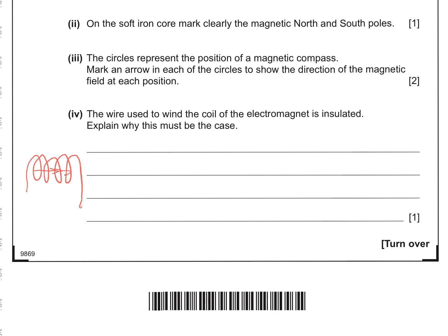Okay, so you're going to want the current to flow around the core and not have short circuits, reducing the looped current. And you certainly don't want it making contact with the iron itself and the iron starting to short circuit the coils and losing all your strength of magnetism. So the coils touching each other would produce short circuits. The iron touching the coils would produce short circuits, and in both cases they would reduce the amount of magnetism produced, because it would reduce the amount of looping current that's going around the iron.